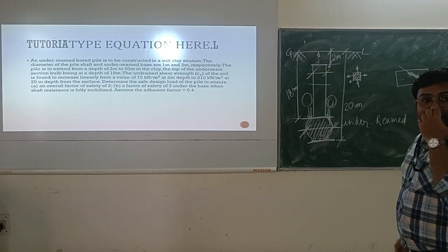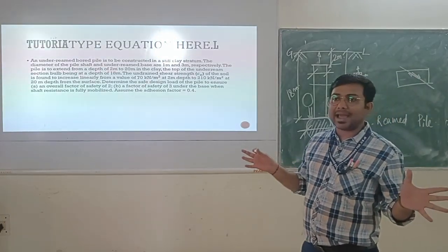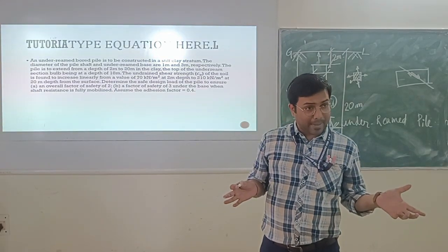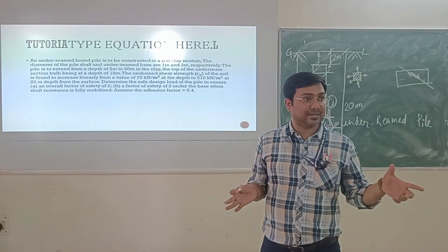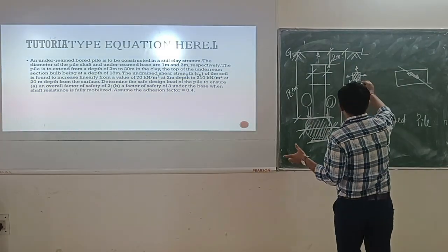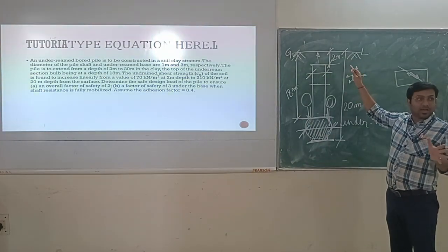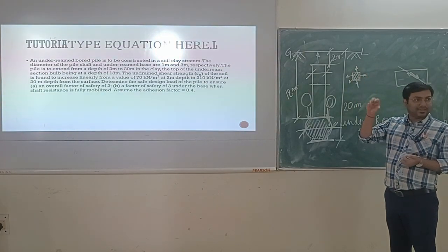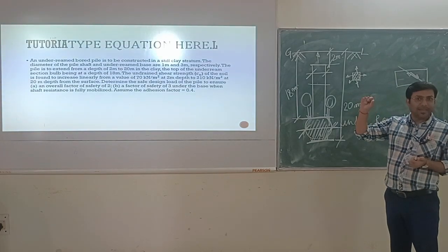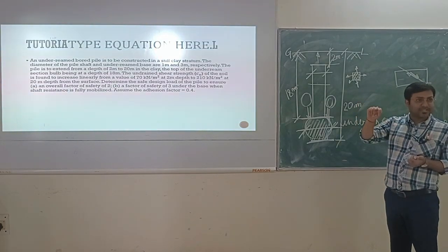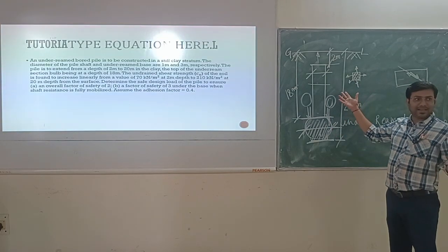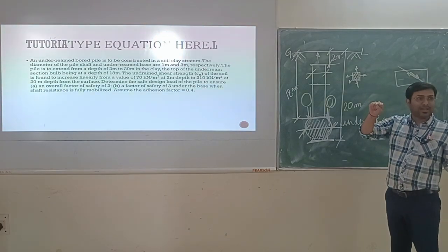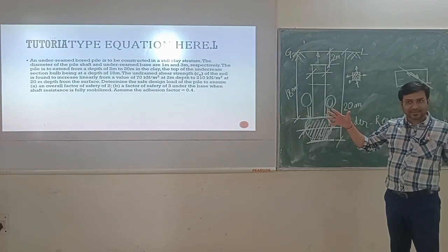Okay, so this is the drained condition, when water can come out from the soil pores, and when that cannot happen, that is called undrained condition. That means when for any reason water cannot come out from the soil sample after application of external pressure. Think of squeezing a sponge: if the sponge is wet and we squeeze it, water will come out. Similarly, in the pores of soil, water is there, you squeeze the soil, water is coming out. That is the drained condition.